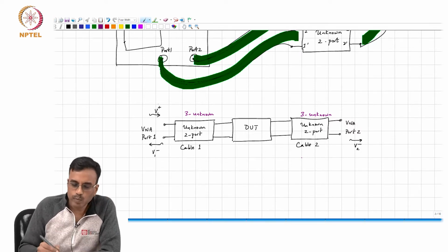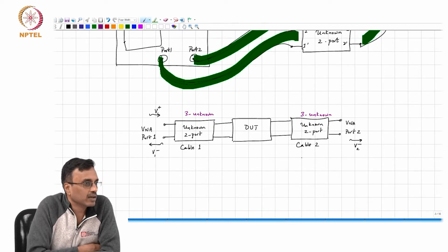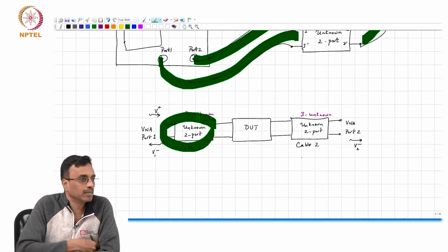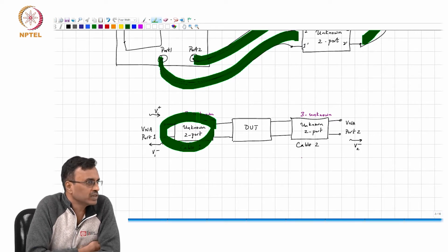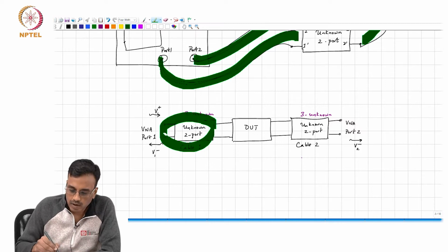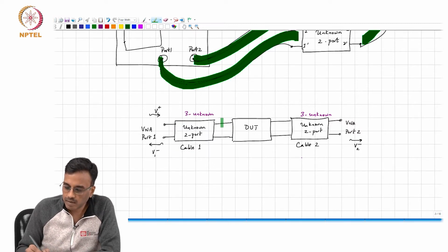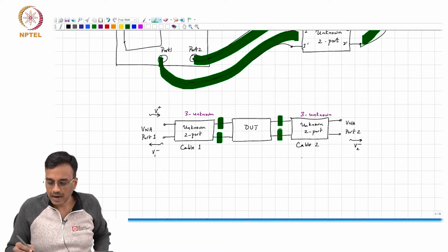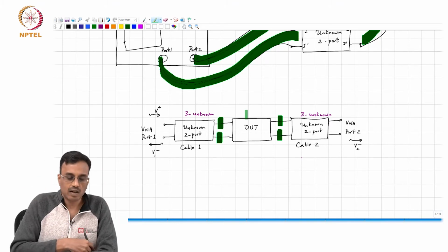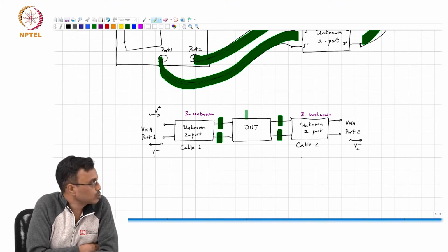No, that's all equivalent to, basically, you are saying that the VNA port is not good, right? That's equivalent to adding an impedance here, which is equivalent to adding something to this unknown 2-port, which is going to get calibrated, correct? So in reality, ideally, if the DUT was not there, what comment can you make about whatever S12 you measure or S21 you measure?